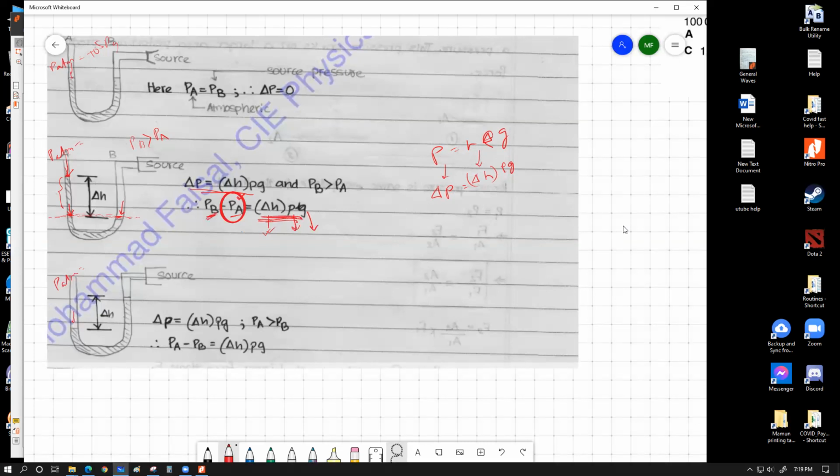That's basically the aim. But what you really need to understand is that the manometer doesn't give you the value of the source pressure directly. It only gives you the difference of those two levels. The manometer gives you the pressure difference of the two sides. Because we know the pressure of one of the sides, the other side's pressure can be calculated.